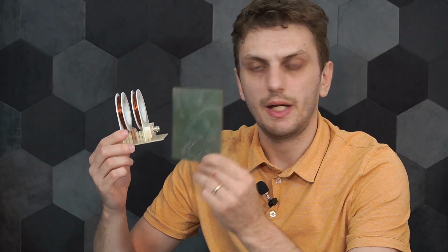Now in the previous video concerning magnetic field shielding, I used a setup with two inductors, one to represent the noise source, the other the sensitive circuit, and shielding was provided by conductive plates. And now what's important to mention about this is that when I placed the conductive plate in between the two inductors, the plate was never grounded. So there was no wire going to ground, or there was no clip behind the scenes. The plate was electrically floating. And for magnetic fields at least, that's not really a problem, because all the currents induced into the plate stay inside the plate.